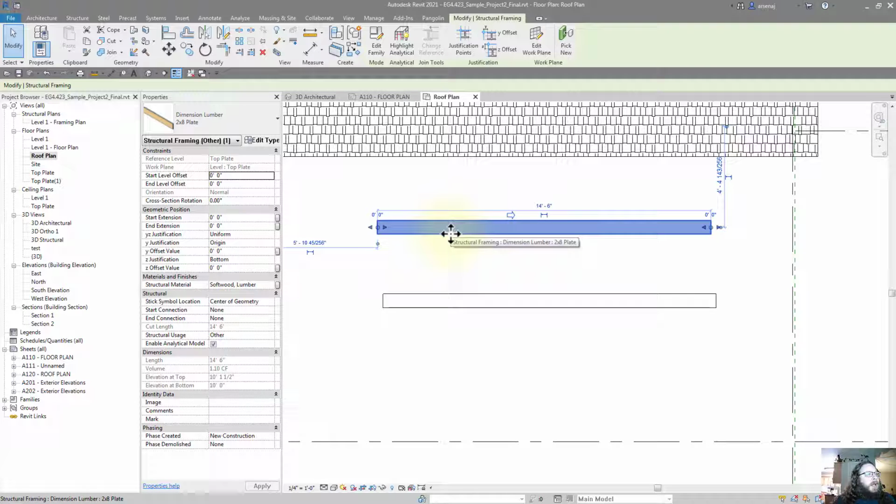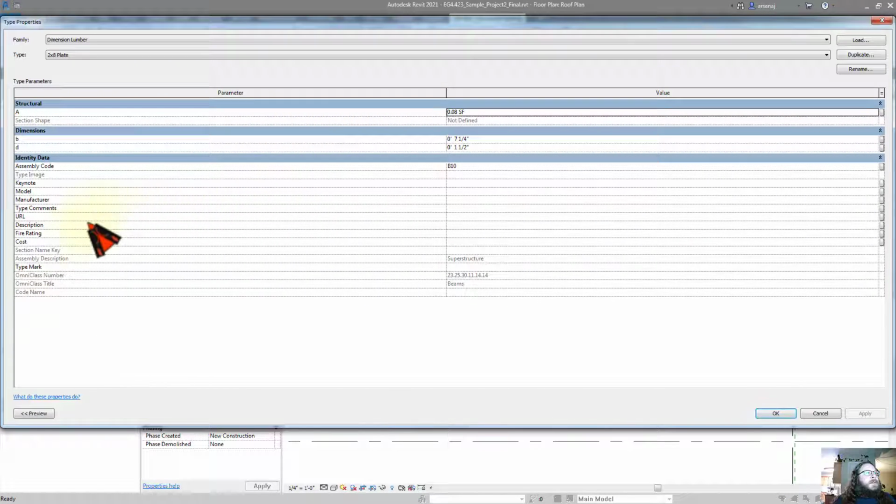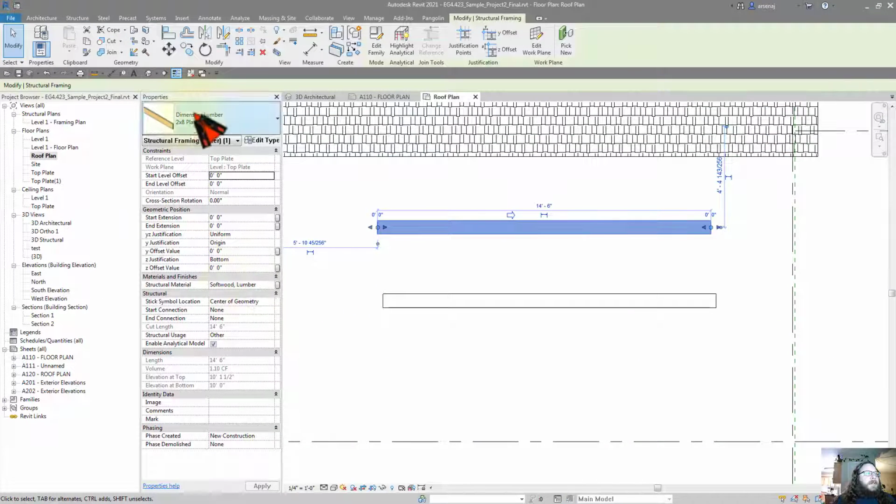let's see here, oh, interesting. So in this beam family, the material, so see how I went to edit type and there was no material. We hit cancel. Some families have the material setting in the properties palette. This means you can have different materials for different instances. So this instance, we could have a different material.